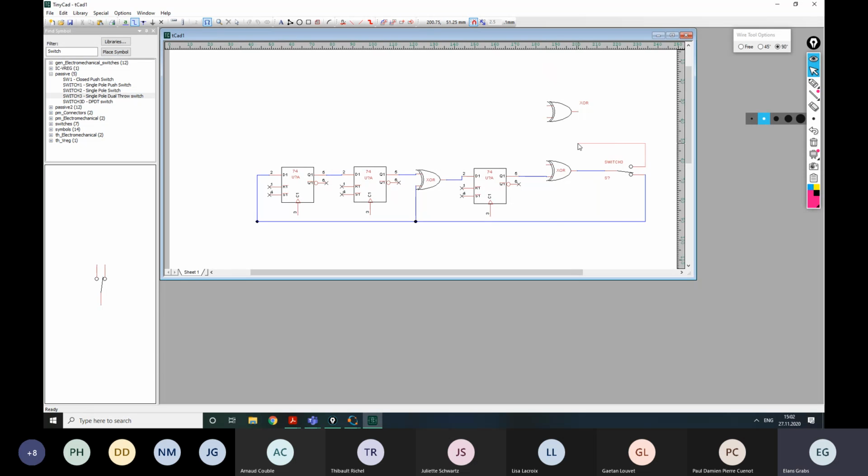While this point connects to this output. So by default, it's unconnected, right? So nothing comes here, and our input data is output at the end of this XOR without changing, because basically here we have 0 and anything plus 0 is that anything. And at the same time, we are feeding the very same data to our dividing schematic, right?